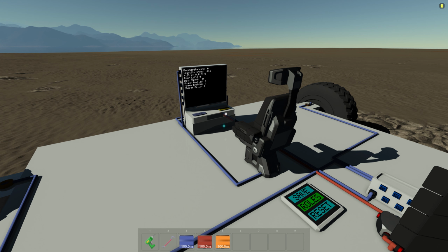In part 3 and part 4, we may get fun, like add a wheelie option, where once you hit a tilt of, I don't know, like 40 degrees, we'll put a toggle switch to enable the mode. If you wheelie up to 40 and this toggle switch is on, it will maintain the wheelie for you. So you can take your finger off the acceleration, and it'll just maintain the wheelie. Another one, we need to deal with maintaining a straight line, and we'll probably use a PID controller for that, so we don't slip around too much driving.